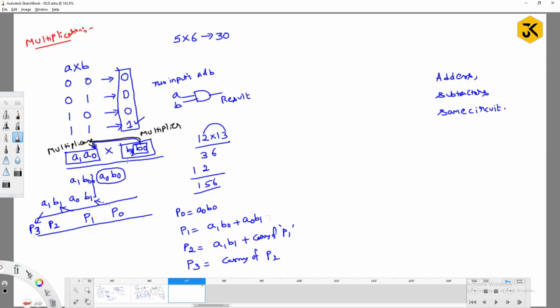And when you are trying to take the next bit of the multiplier, you are going to shift one bit, and then you are going to perform multiplication, right? Guys, assume that in the multiplier, if the selected bit is a 0, then we are going to simply place all zeros, right? If the selected bit from the multiplier is 1, after performing the operation, you are going to get the result as the multiplicand. Am I right?